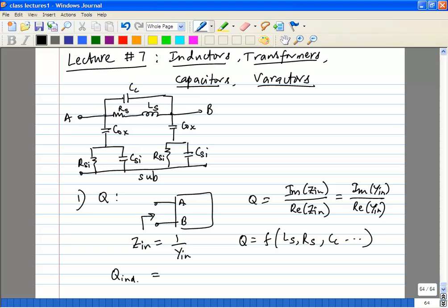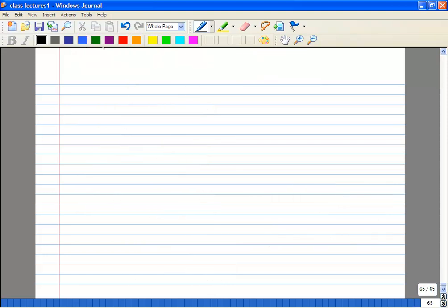But the other important thing to notice: if you have some capacitance, we looked at it as omega L minus 1 over omega C over R, so you'll get some expression like this. You have some inductive effects, some capacitive effects, over the resistive effects. This is valid only as far as the system is an inductor. Beyond that, the numerator will get negative. So when you plot it, you will see some negative Qs in your simulations, but you just have to keep this in mind. The Q definition is no longer valid beyond that. Now the other thing we looked at is the self-resonant frequency.